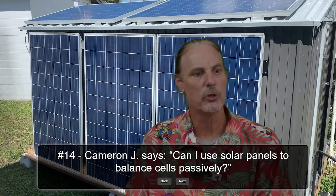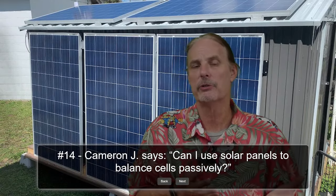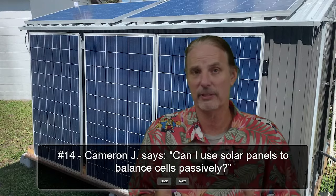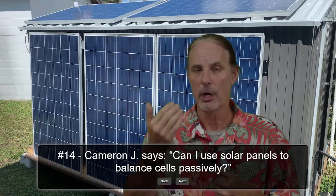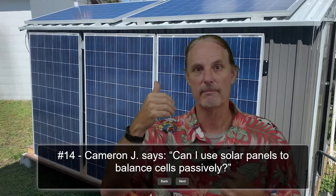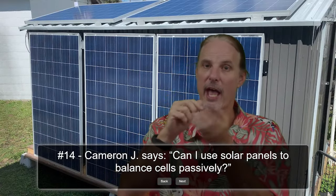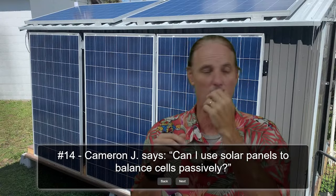Say I use solar. Can I use solar panels to balance cells passively? Absolutely. So the solar panels will go into the charge controller. The charge controller should use those panels to passively balance. We've talked about passive balancing. This is where it's just going to take the highest cell voltage that you have, and it's just going to burn off some of that voltage and heat, and then new voltage will come in to charge the lower ones, as opposed to the active, where it would take that voltage from the high one and give it to the low one.